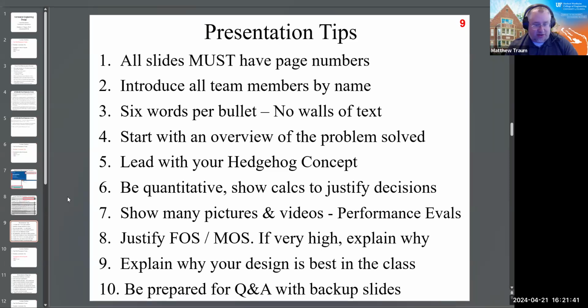In the automotive industry, you might consider a factor of safety of something like 2 or 3. They still have weight and cost concerns, but they're not nearly as severe as in the aerospace industry. And of course, in the auto industry, they can take on less risk than they can in the aerospace industry. So factors of safety are going to be higher.